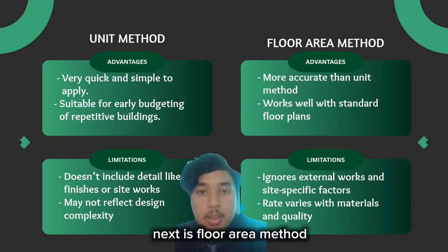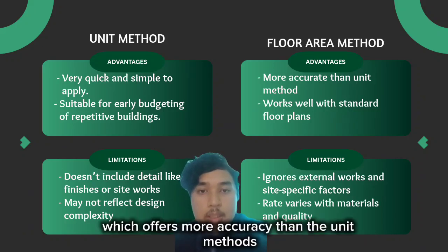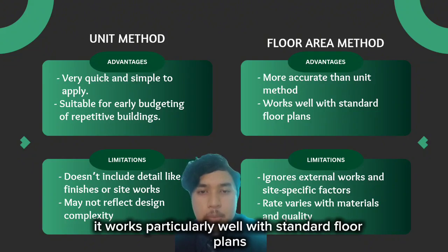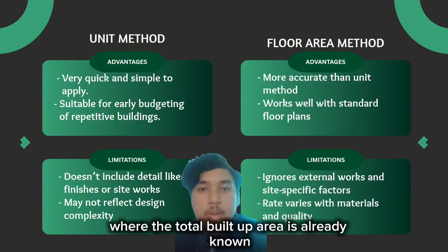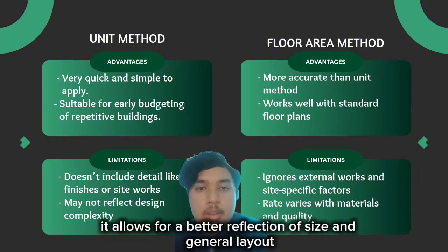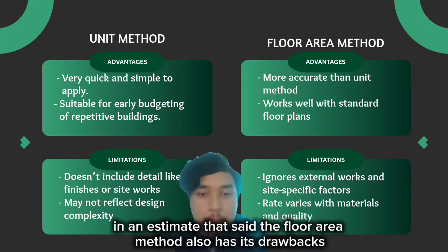Next is the floor area method, which offers more accuracy than the unit method. It works particularly well with standard floor plans, such as bungalows or semi-detached houses, where the total built-up area is already known. It allows for a better reflection of size and general layout in the estimate.